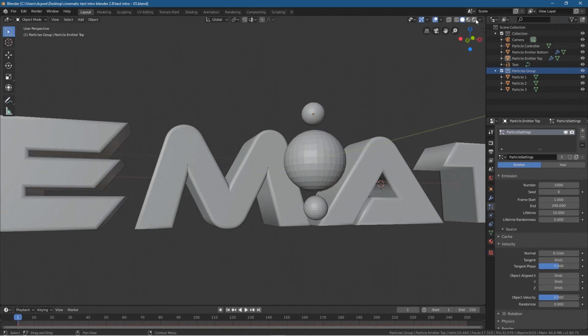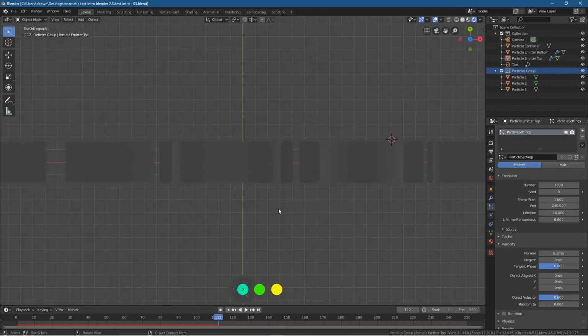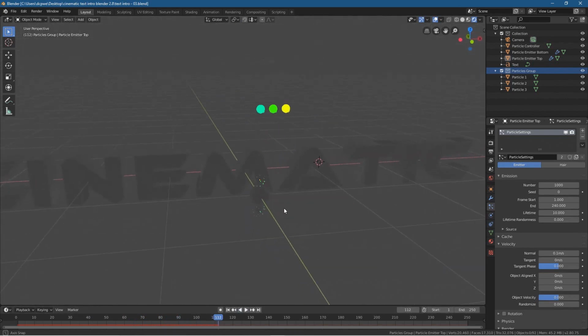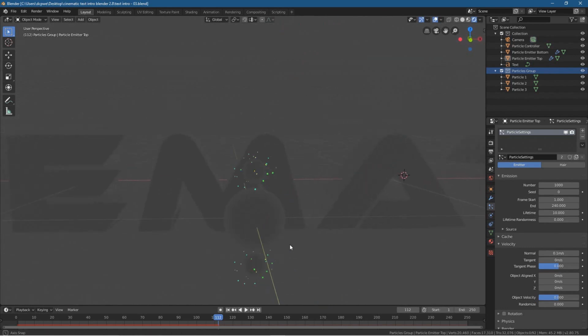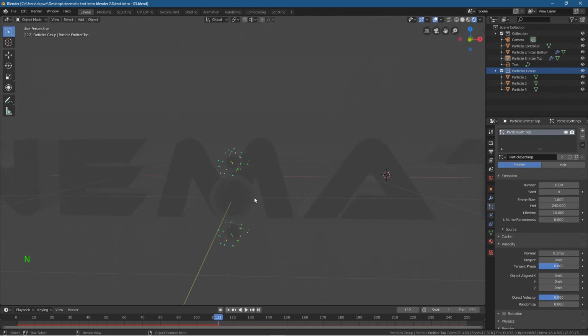Now if we go back into Render View and click Play, you can see they're both behaving the same. Why it does that, I think it's a little bug, I'm not quite sure. I haven't worked it out, but that seems to fix the problem. So if you're ever using particles and one's behaving differently, even though you copied it over, then that might be a problem. Just go and save the work as a new file and then reopen it, and it should be fine. So now that I've reopened it, let me just make sure my screencast keys are on. Let's just see, they're on.